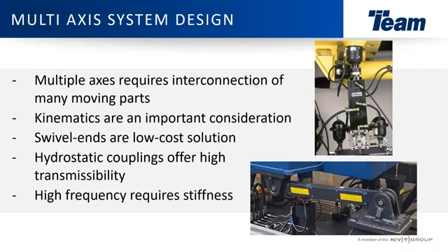The reason for doing this is it's more or less the cheaper solution to provide the minimum amount of constraint for all of the motions. And it gives you the full capability of all 6 degrees of freedom. By actuating the exciters in phase or out of phase, you can reproduce all of those motions with minimal actuators.